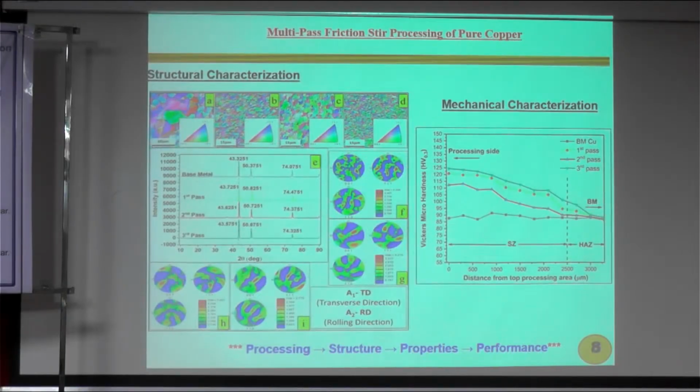These two are big differences there. Even though both come under the noble gases, argon's ionization potential is 15.6 electron volts, but in the case of helium it is 22.5. Then why are we more interested in the ionization potential? If it is a higher ionization potential, lesser heat input is sufficient.